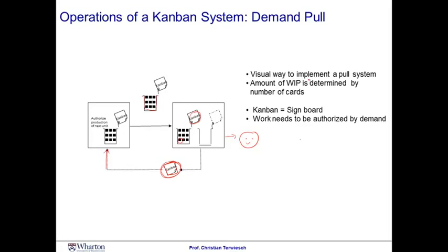By definition, the work in process inventory is never bigger than the number of Kanban cards. This allows us to keep a cap on inventory and to control the inventory level, just like with the boat on the river on the previous slide. In the early days of the process, when there are still defects or other problems, we issue an extra couple of cards. As the process gets better, we remove some cards from the system and we put more pressure on the process improvement.